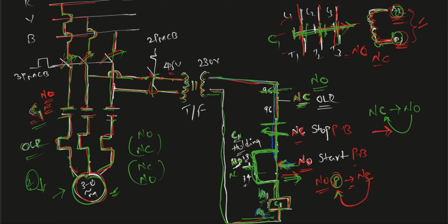Your voltage is stopped over here and your motor is protected from overcurrent. The A1, A2 terminals will not receive any power, your C1 contactor de-energizes and opens again, so voltage does not reach your motor. This is the protection given to the motor.